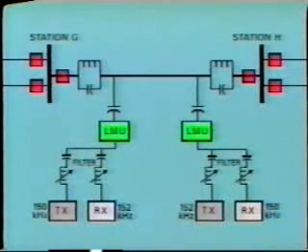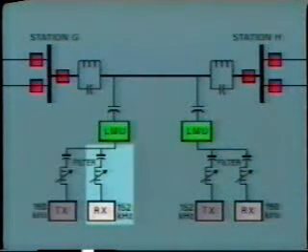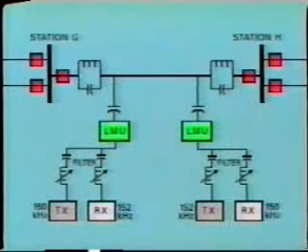Aren't the transmitters and receivers fitted with filters tuned to their specific channel frequency? For example, 150 kilohertz on this transmitter and 152 kilohertz on this coupled receiver. Unfortunately, when the frequencies are so close together, some of the 150 kilohertz transmitted signal will leak through into the receiver.